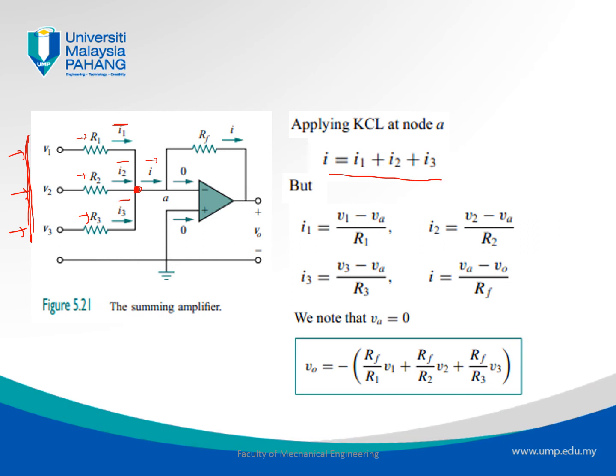So it's explained here. Then that I goes into the thing that we've seen in the previous slide with inverting op amps, right? So it goes into the inverting terminal, and again the non-inverting terminal is just connected to the ground, and then in the connection from the inverting terminal to the output, we will have a feedback resistance RF, right?